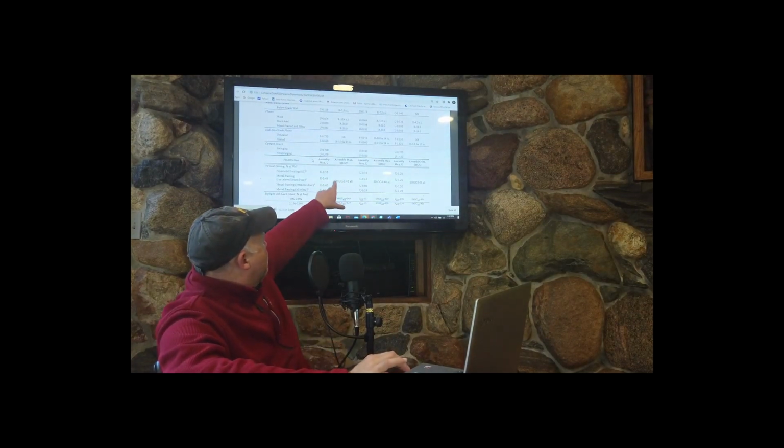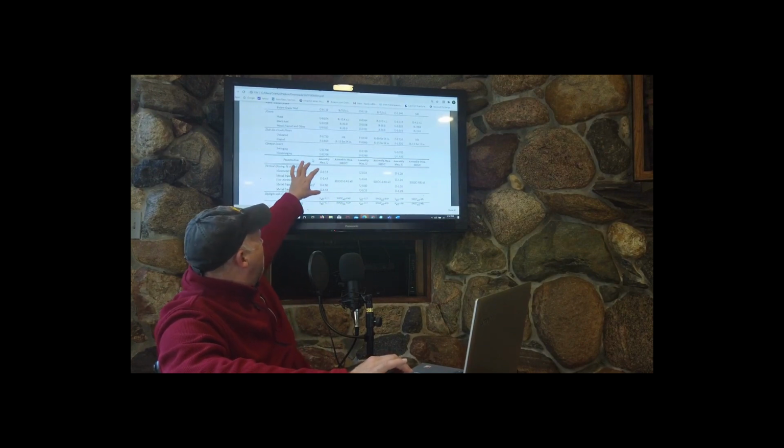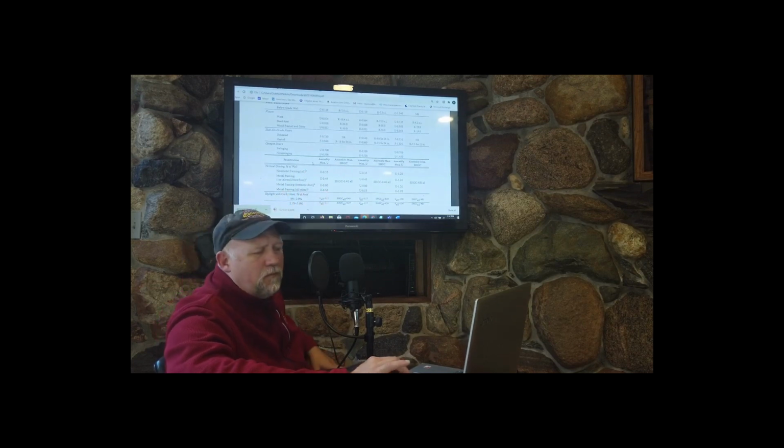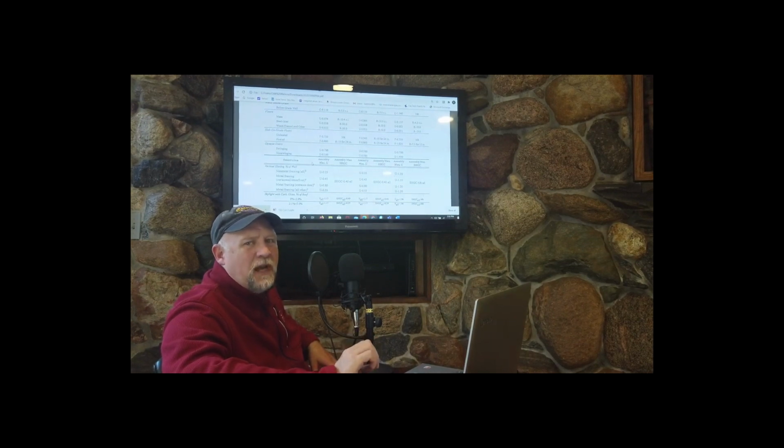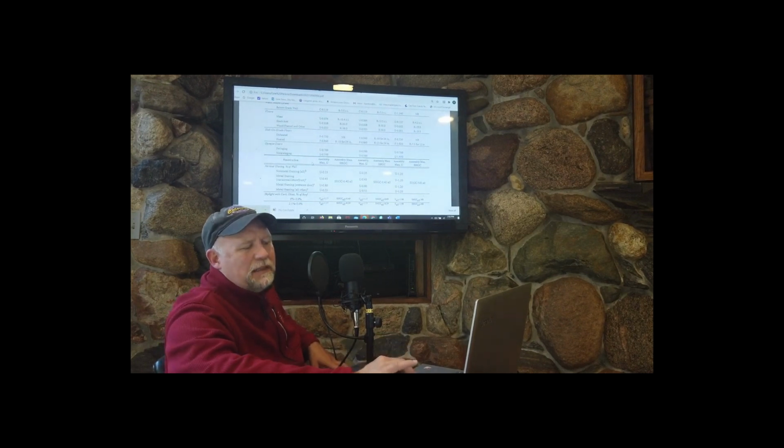Anyway, there's a conversion factor to change this to a shading coefficient. But these are pretty decent. A U value of 0.45, or if it's metal framing, all other 0.55. Those are at the very minimum. Those are dual pane glass windows as a start and some type of a thermally broken window frame. It's a good start. You can get a lot better, but that's decent.